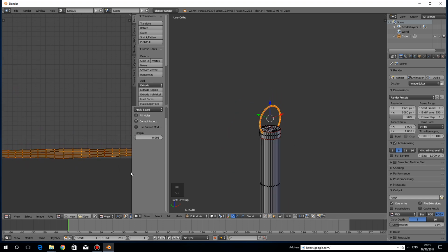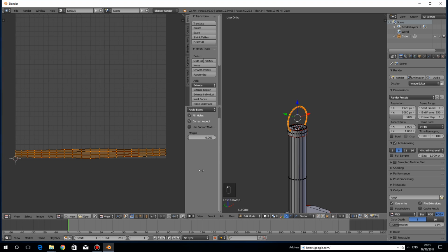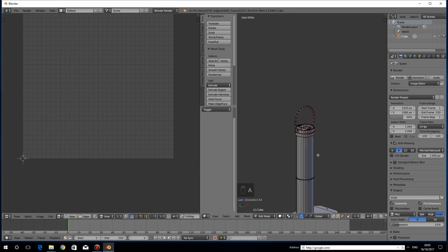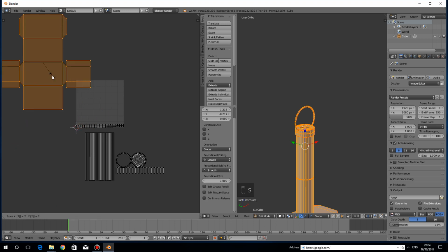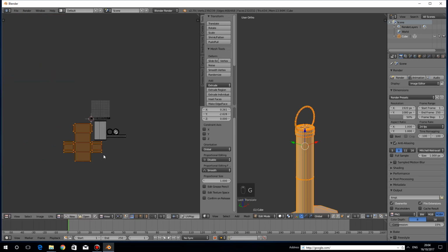Okay, so now let's sort this UV out and lay it out a bit. So we'll select everything on here so we can see everything in here, and as you can see, it's all nicely laid out there. So what we want to do is hover over this area, press L to select the whole object, press G to move it, and what I will do is scale that by 2 for now, and then see how it goes.